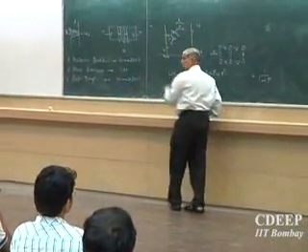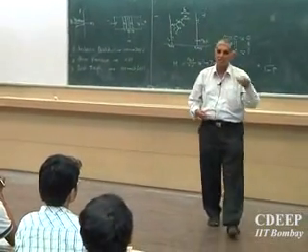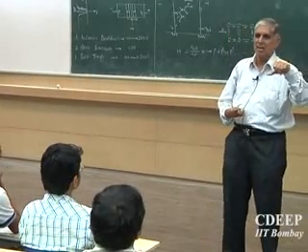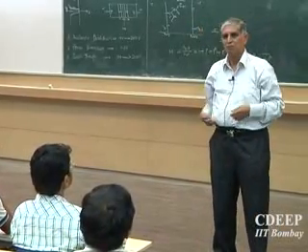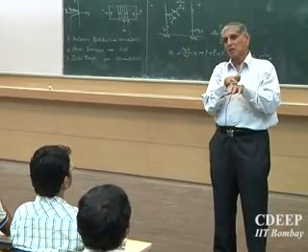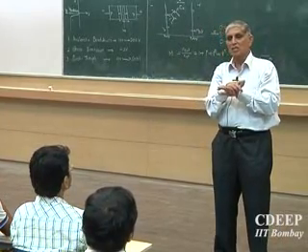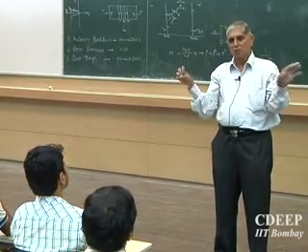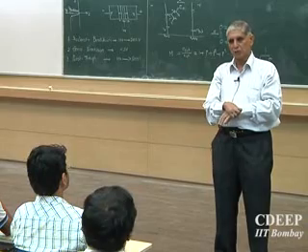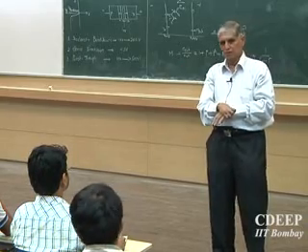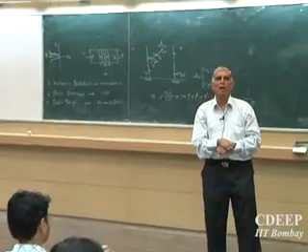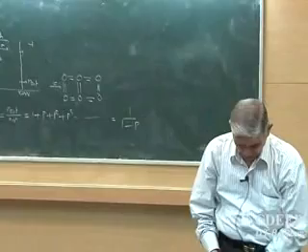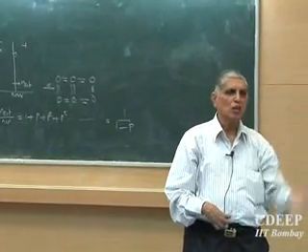Now this electron itself is available to you. It also will accelerate. That is how I am taking N out by N in. Whatever I initially introduced will get multiplied now. That itself will move. Some may recombine as well because their recombination probability is not 0. But most of them, before they recombine, will be separated because of the electric field available. So this is essentially the reason why, at certain large values of reverse bias voltage, suddenly heavy current starts.